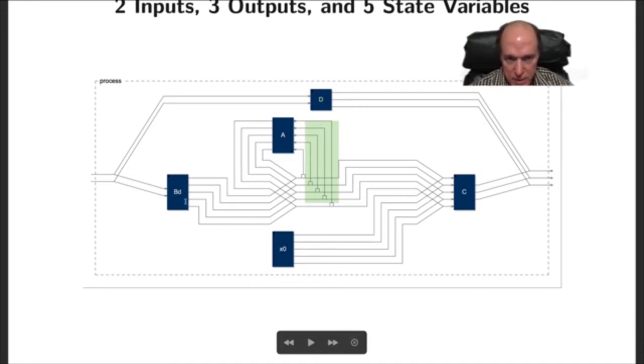All right, so here's our B matrix. It comes in. So this is your state. These delay elements contain the state variables, and the A matrix feeds back around, and then you sum. So this is x of n plus 1 summing with B times U, the input, and that forms the next state. And then the C matrix takes a linear combination of the states and puts it out. On the first sample, time 0, it's C times x0 that goes out. That's your time 0 output. You also add D times U to that.